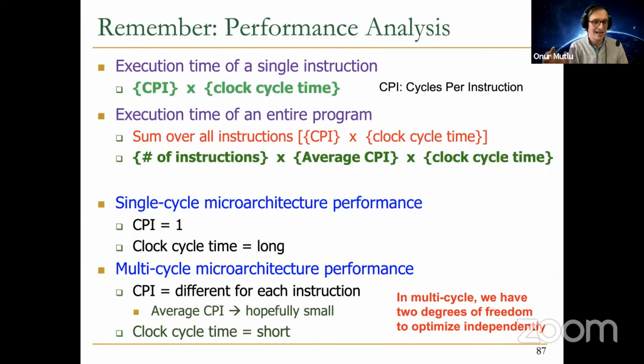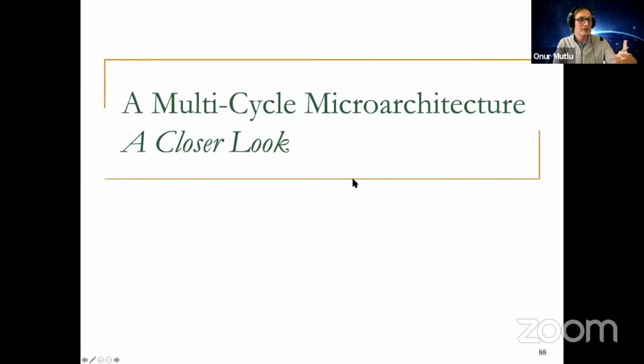The sequencing overhead at some point becomes too large: if you reduce the clock cycle time too much, most of the clock cycle time is wasted on that sequencing overhead. And you don't want to be at that level. You really want most of your clock cycle time to be doing useful work. Okay. So recall the timing and verification lecture if you're really interested in these concepts. That's why it's so fundamental.